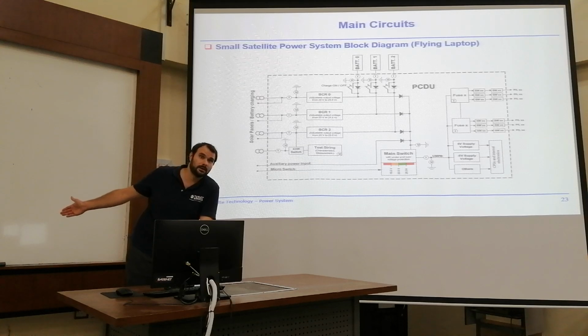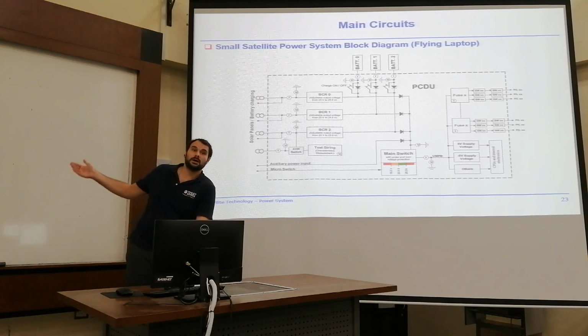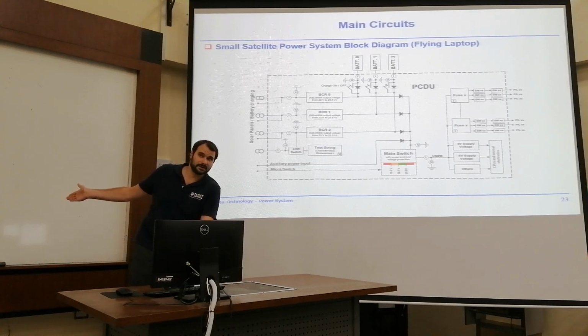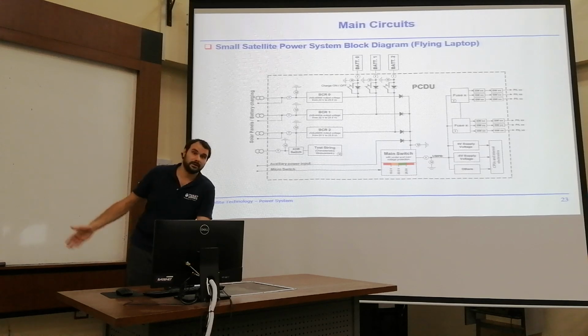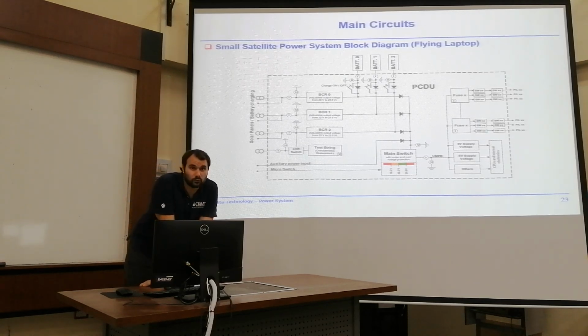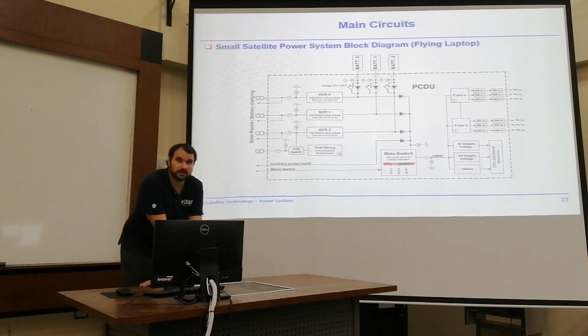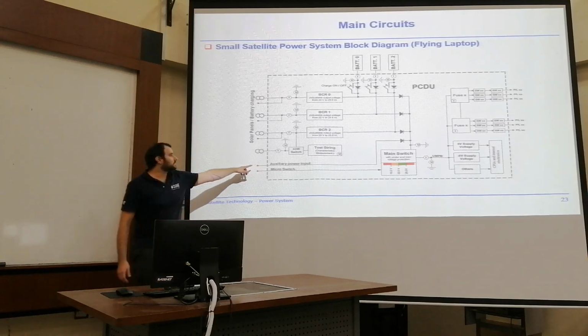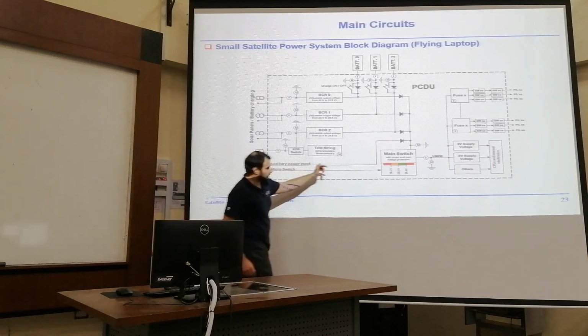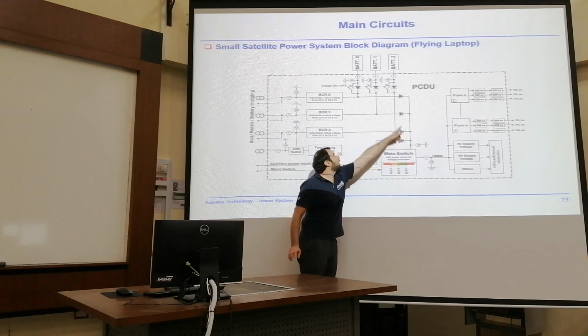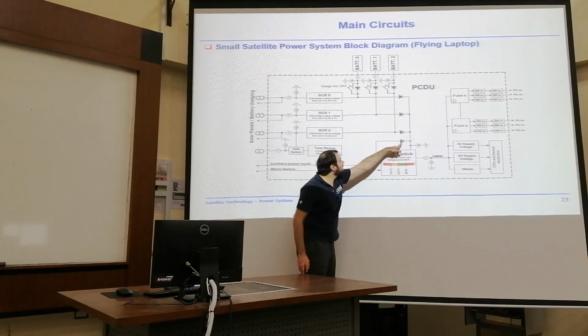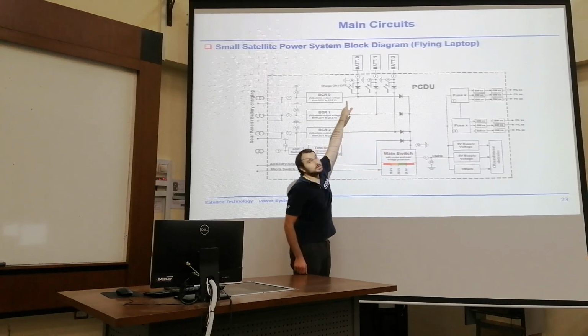That means you need to find a way to charge your batteries. I doubt that you want to bring an artificial sun into your clean room. You can do that for testing purposes, with huge lamps, they're really warm and bright. But usually, you're better off just having an auxiliary power input, feeding in here over the diode, and then if you close all the switches, from here you can directly charge the batteries.